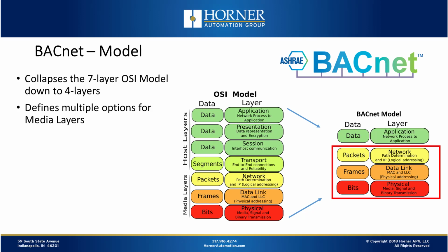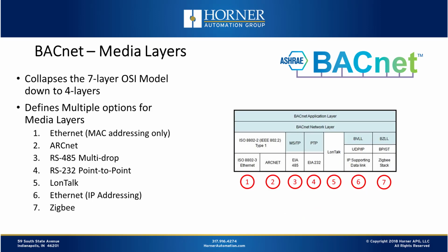And like ODVA, the organization that effectively manages Ethernet IP and DeviceNet and ControlNet and those networks, the BACnet folks have made sure that they supported multiple media layers, so that not only can you support a protocol over Ethernet, for instance, they actually have a couple different ways of doing that here, but BACnet really is one of the most flexible networks in terms of the physical media that is used for exchanging data. They support officially 7 different media layers with this protocol.